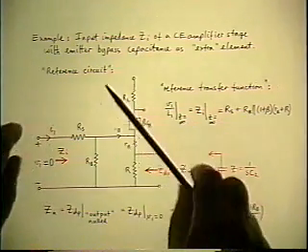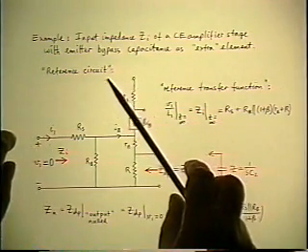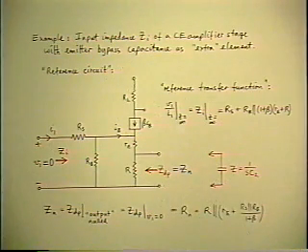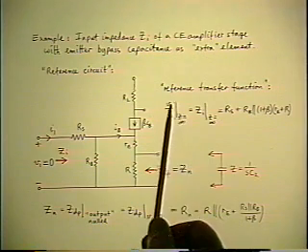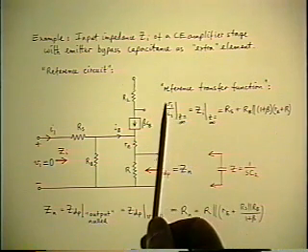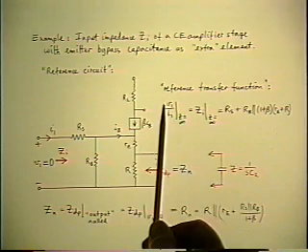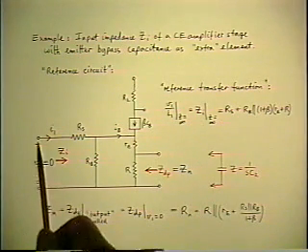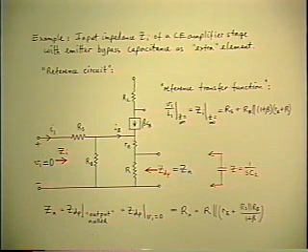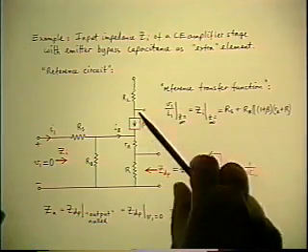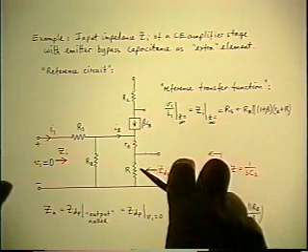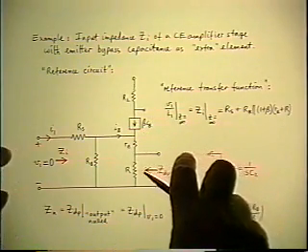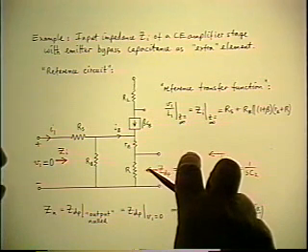And we're going to adjust those two inputs in order to null the output. What is the output? The output is the quantity in the numerator of the transfer function of interest, which is V1. So you can visualize a voltmeter hung over the input across the current source I1, and we're adjusting the I1 and the other independent source until that voltmeter hung across the current source out here goes to 0.